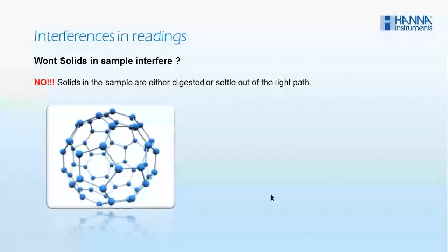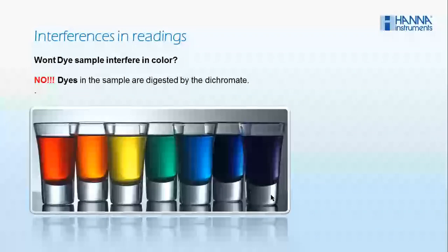And most important, will dye color interfere in your reading? The answer here is no. The dye color will never interfere in the COD readings. As the dye comes in contact with the dichromate, it gets readily digested, and hence it will never allow color to interfere with your reading.